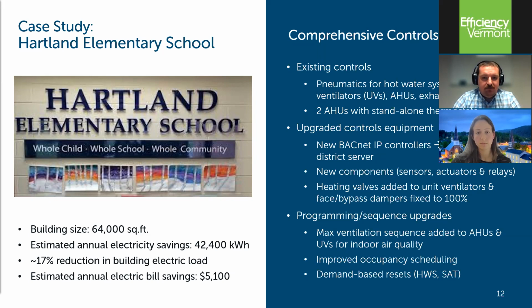And being that it was BACnet IP devices on site, we didn't need any supervisory controllers or gateway devices. We were able to go directly to the server with the new controllers. All the pneumatic components were replaced, so sensors, actuators, brand new valves, for all the equipment. For the 2 air handling units that had standalone thermostats, we reused some of the actuators and relays, but added